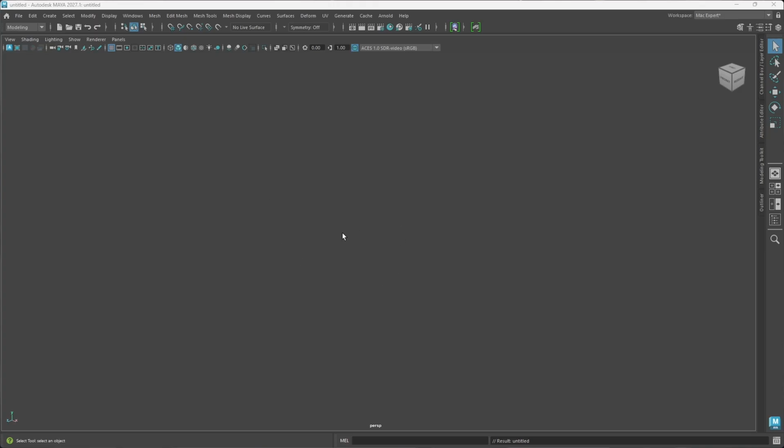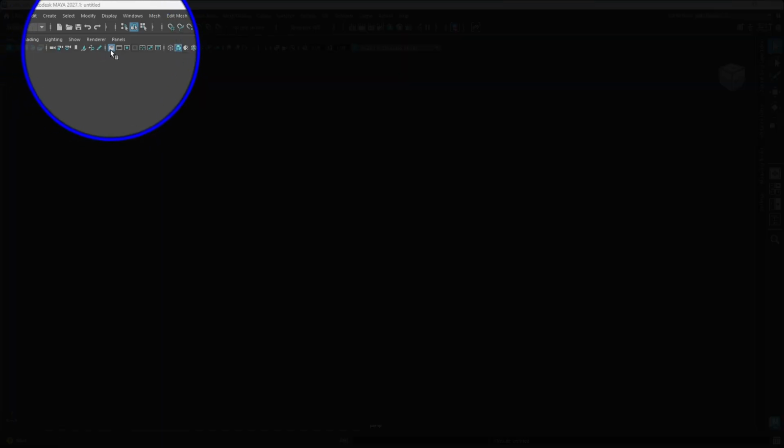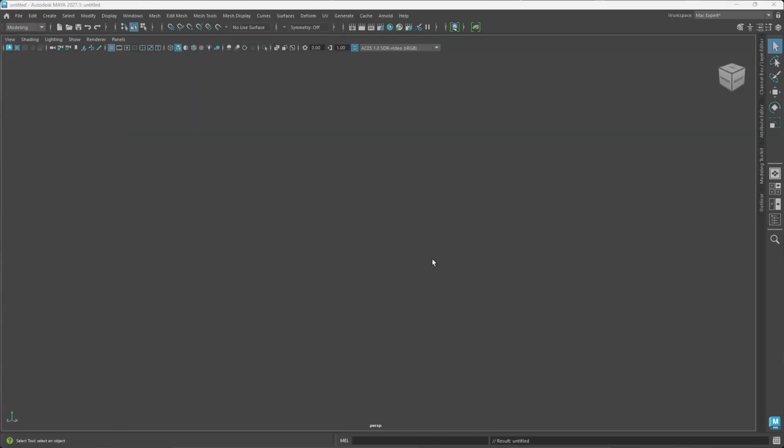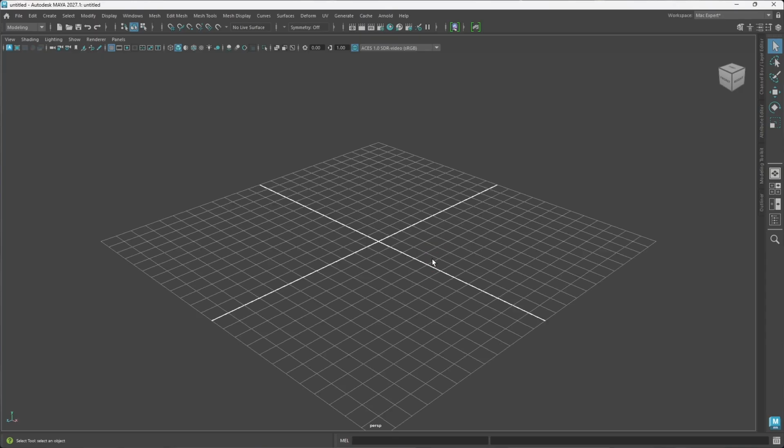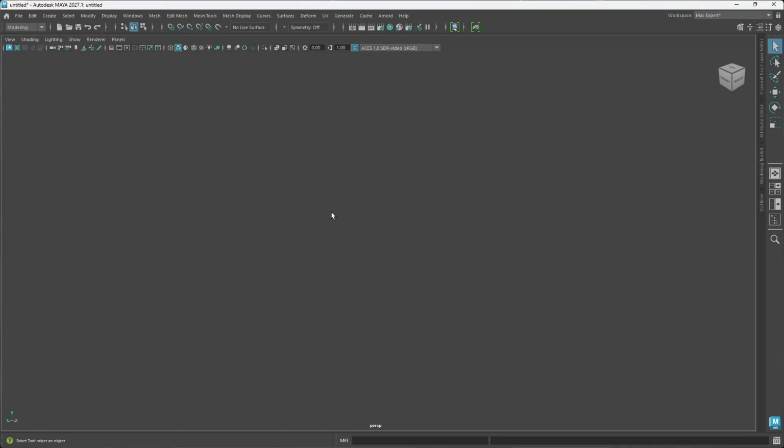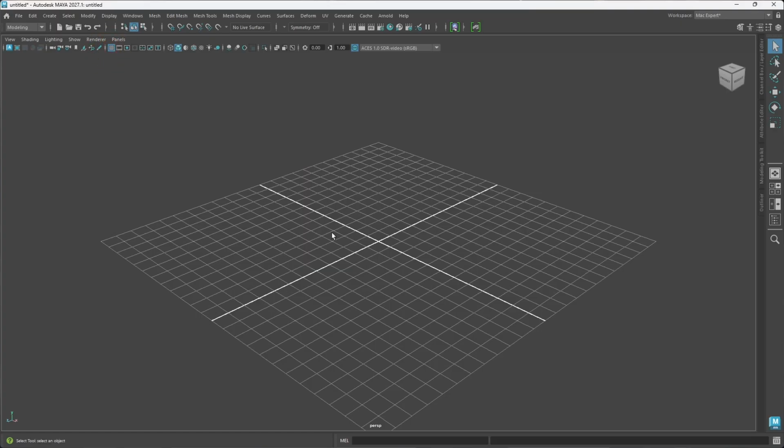Now, you can notice that my grid is not here. If you look at this part here, you see that the grid is turned on, but it is not showing in my scene. That is because I turned it off with the shortcut, which is Alt G. Now you can see the grid here. If you are using my workspace and your grid is not available, just make use of this technique to bring it back. They work independently. If you hide it with Alt G, this won't work, and if you hide it with this method, Alt G will work.